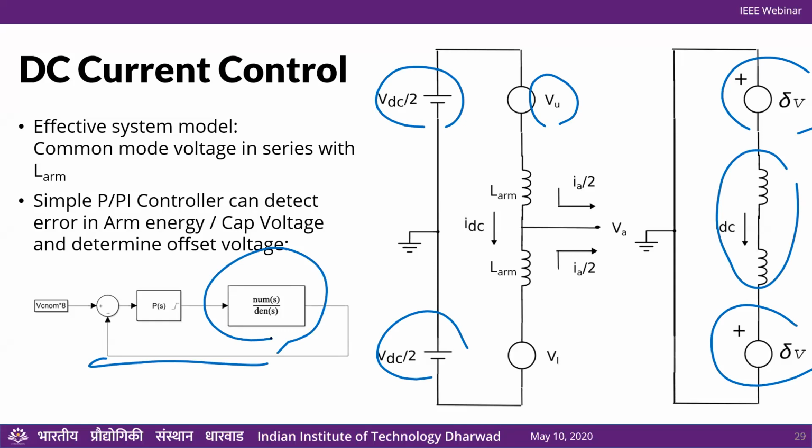Just put your transfer function, a simple first order system, design the PI, and you can figure out what your controller should look like. So this transfer function has these two inductors, and it has an inbuilt capacitor that is integrating that charge. So that's your transfer function. Design the PI, and what is the average voltage that we are trying to hit? That is, let's say, the total voltage. We'll see that in the MATLAB model when we get to that.